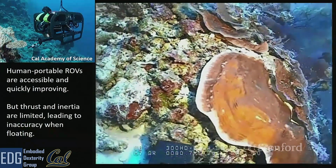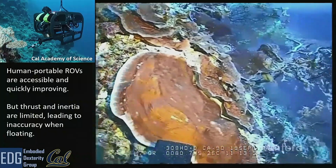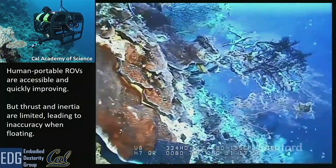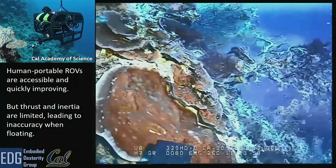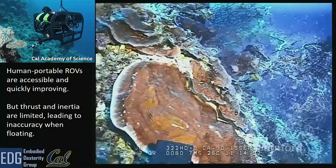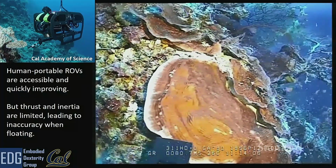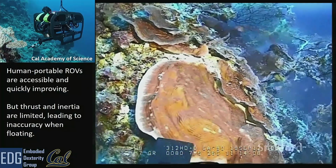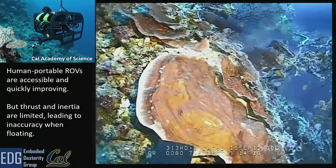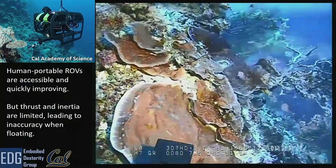There's a problem with small platforms though. They're really hard to control. They have less thrust, their moment arms aren't quite as large, and so they're really hard to control when you have a very turbulent environment. So this is courtesy of the Cal Academy of Science. They have this little rover with a gripper on it, and they're trying to grasp this thing. If we watched it for probably half an hour, eventually we'd smash into it, break it a whole lot, and then swim away without a sample. And so this can be really frustrating.